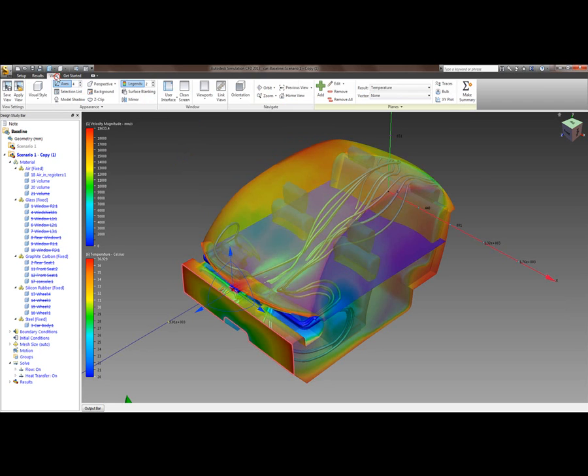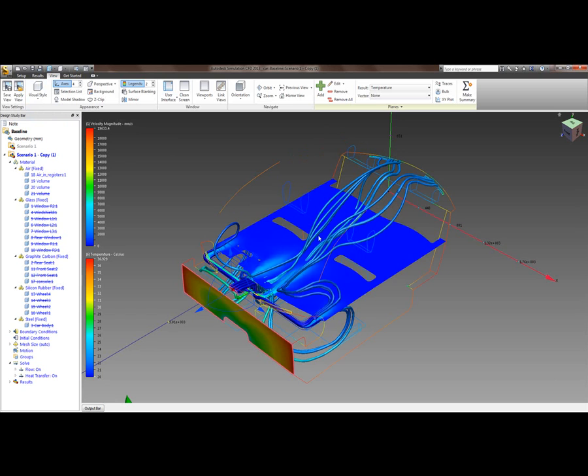If we now look at it, we can change different views, so I can just put an outline. You can now see the heat coming through and the temperature and how it's being pushed around, so it's coming down and it's a little bit warmer, as we saw at the footwell when we put the trace points in earlier. So you can see that kind of change in temperature.